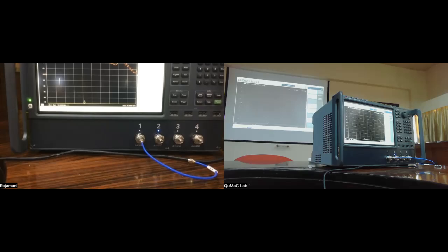Usually for typical measurements where you're not expecting a huge change in power from input to output, something around 0 dBm is a good number to work with. That's usually well within the maximum power the system can put out. And this is the, so 20 dBm. Okay. I guess I have not introduced this term so far. So this is not 0 dB. You see, it says 0 dB, small m. Okay. This is an absolute unit defined in a relative way.